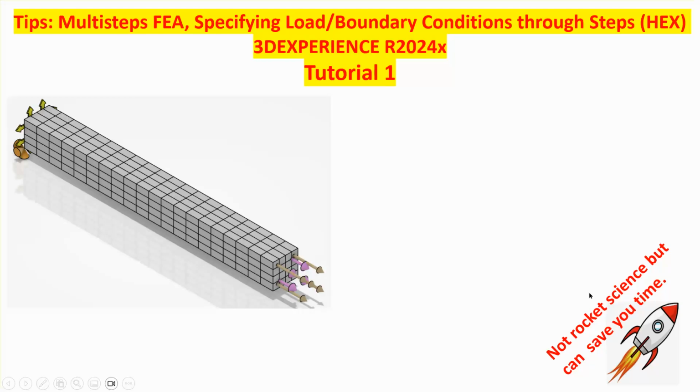It's an axially loaded member, and I don't want to clamp the left side of it because then the stress distribution is not going to be uniform through this thing. So what I'm doing on the left side, as you'll see in a minute, I will just leave it so that there is no local stress distribution. And on the right side, I apply either a translation, a force, or pressure.